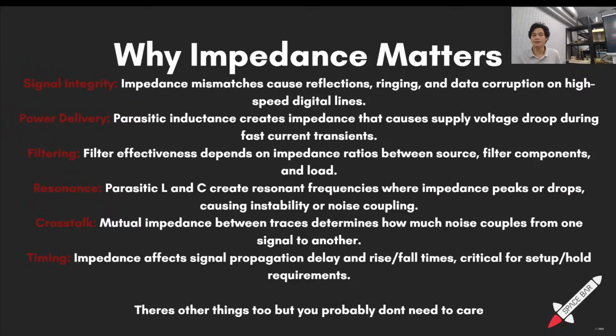So basically it is saying that I have two traces next to each other, they are turning on and off really fast, so there is a changing magnetic field, and a magnetic field can induce voltage in other traces, right? So this trace is going to induce a new signal in the other trace. It's a weak signal, but it's still there and it's causing problems.